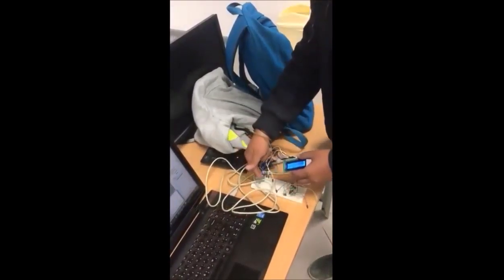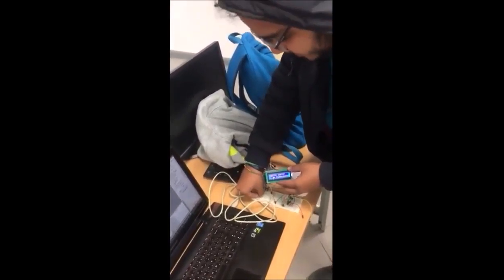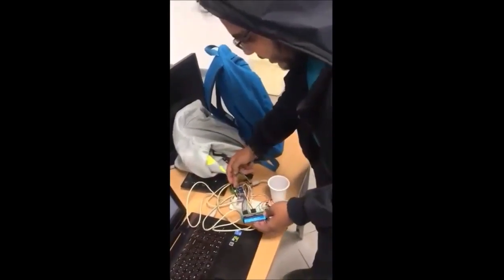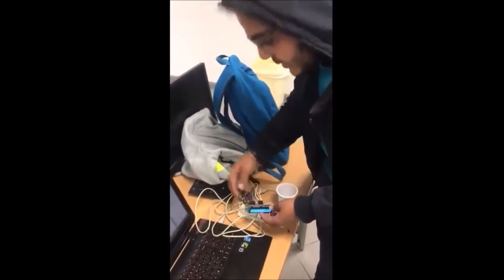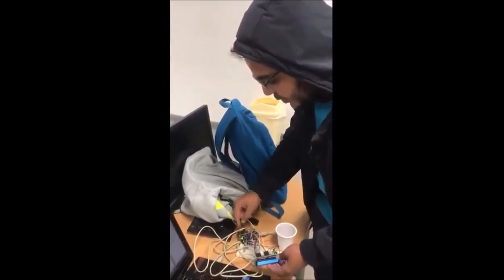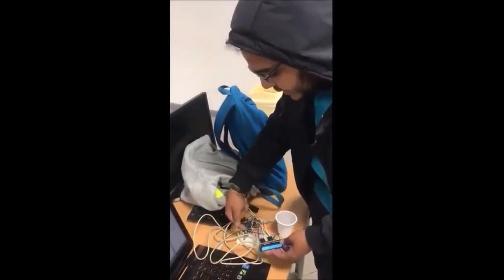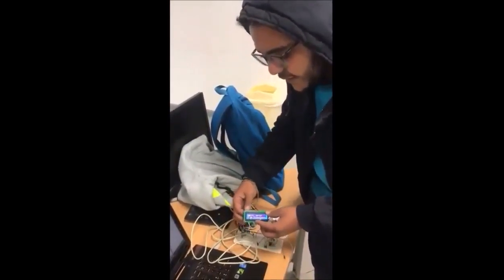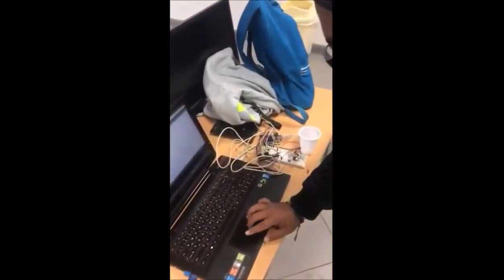My part simply is about connecting the LCD to the Arduino. So the LCD, we put it into a resistor over here to control the brightness of the LCD. After that, we connected the 4 pins to the 4 data pins, and here are 2 pins, enable and reset, and the 2 power pins from the Arduino connected here to the resistor, then from the resistor to the power of the LCD. After all of that, it goes to the code.